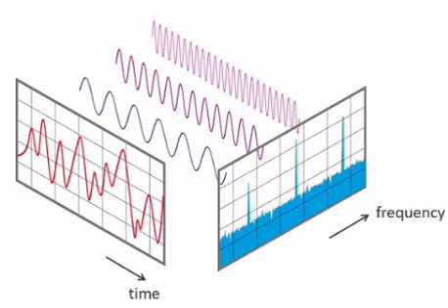Delta of t minus t naught, e power minus s t naught, for all s. cos omega naught t u of t, s by s square plus omega naught square, real part of s greater than 0. sin omega naught t u of t, omega naught by s square plus omega naught square, real part of s greater than 0. e power minus alpha t cos omega naught t u of t, s plus alpha by s plus alpha whole square plus omega naught square, real part of s greater than minus alpha. e power minus alpha t sin omega naught t u of t, omega naught by s plus alpha square plus omega naught square, real part of s greater than minus alpha. u n of t equal to d power n delta of t by dt power n, s power n for all s.